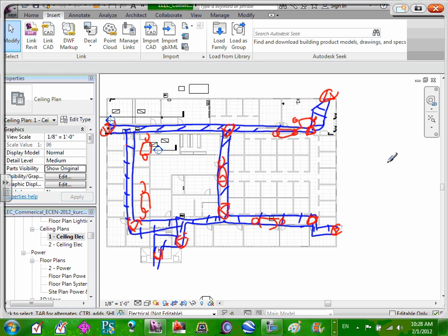But there's a relay up in the ceiling that says when we lose power, that's my emergency fixture and it's going to fail on. So even if the lights are off in that room, that fixture will come on when the generator comes on. Does that fail over to a separate UPS or generator powered circuit? Yes.